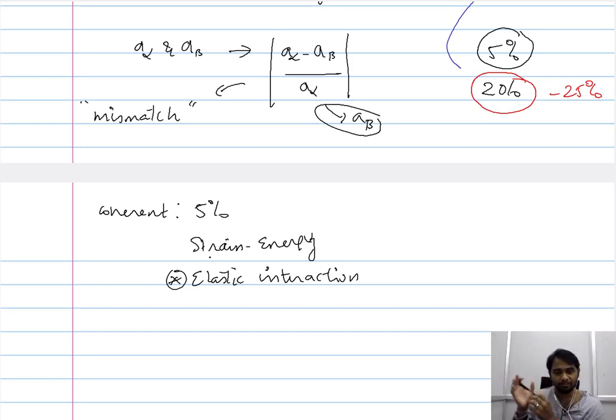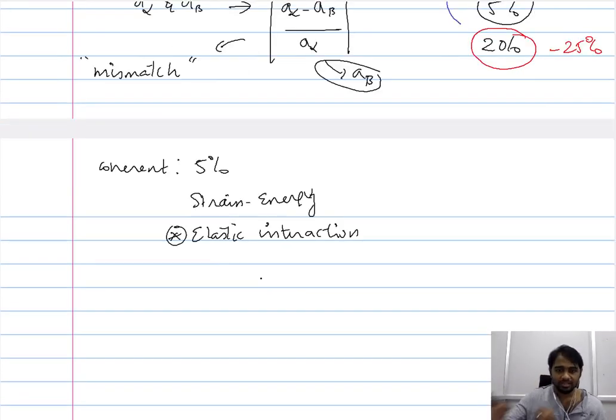So this particle impedes the dislocation. Additionally, this interaction is largely confined to the interface alone. Once the dislocation moves into the particle, the way it behaves considerably varies. Let me repeat, this particular interaction is confined to the interface between the particle and the parent phase alone.